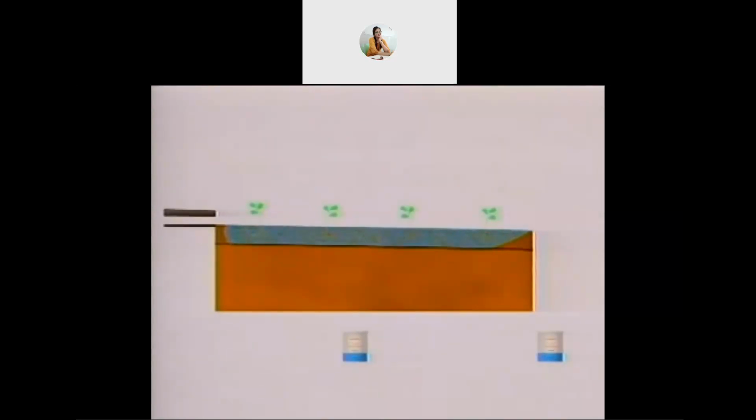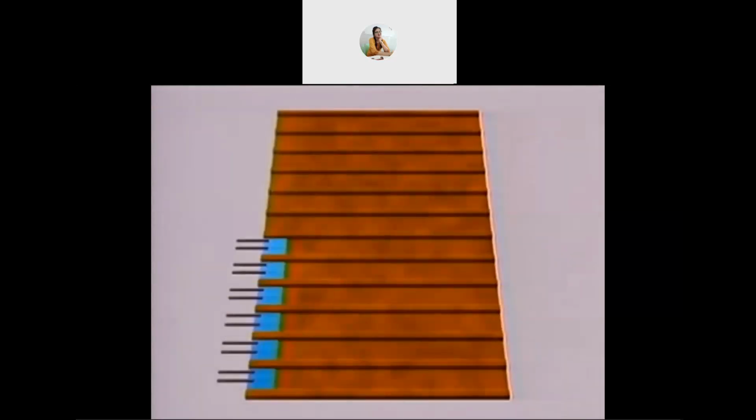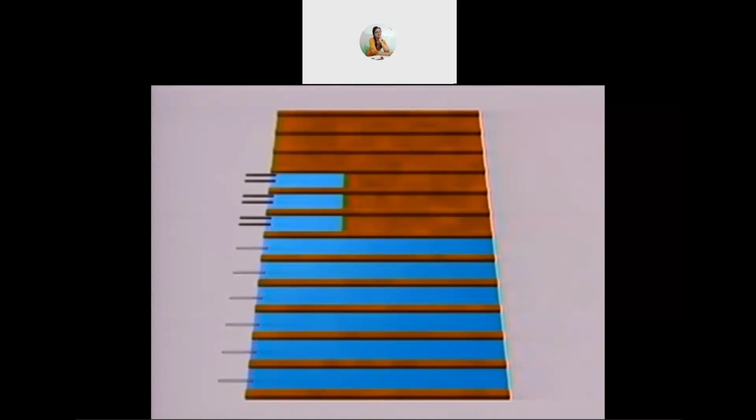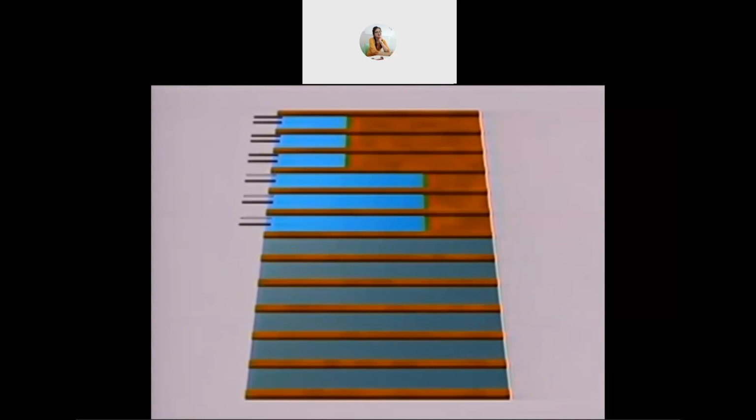Here's a look at the whole field. Let's say you start your first set with 8 tubes. When the water is 2/3 of the way down the row, you move half of the tubes to a new set. When the first set is complete, move the other half to another new set. Then remove half the tubes from the first new set, continuing down the field.